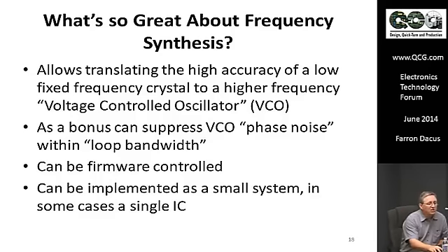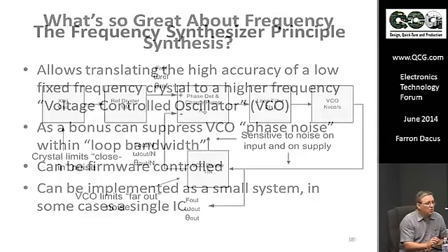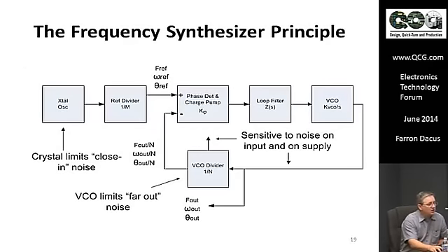And these days you can get them in a single chip. They may be a noisy VCO, but that suppression inside the noise bandwidth allows it to work.